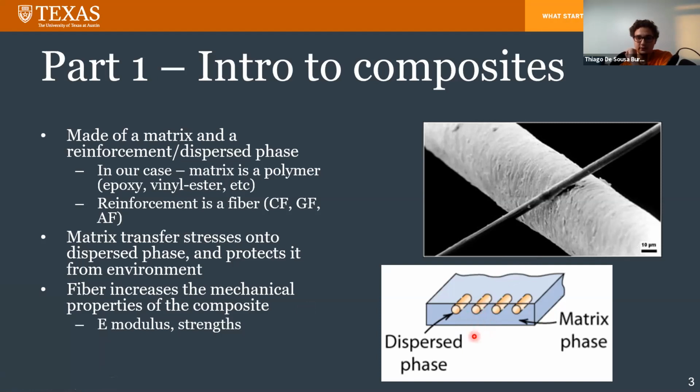So in that direction I would have really high strength. And in this direction, the fibers are actually trying to separate from each other. So this distance is trying to increase. And in that case, the polymer, the matrix, is the one that's going to determine the strength the most. So that's also why it's important for us to pick a matrix that is not very weak, but just weak enough for us.